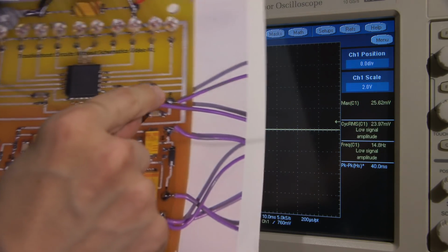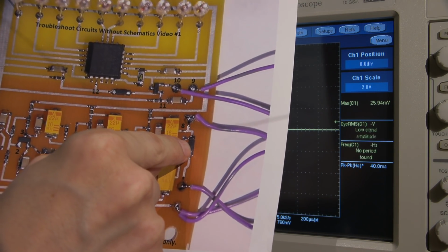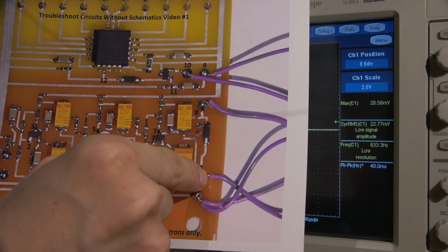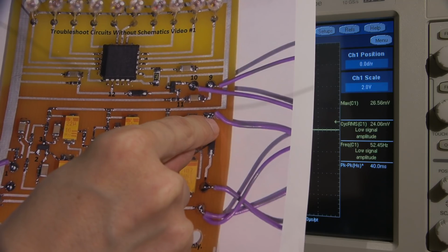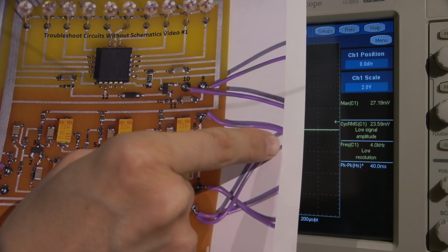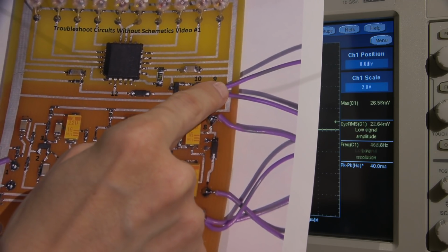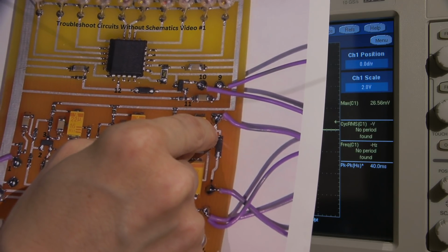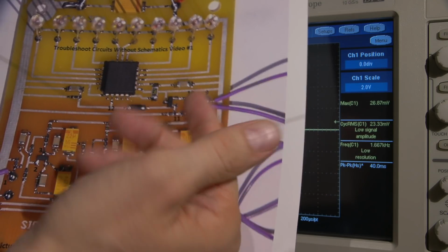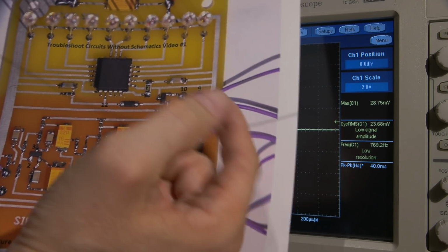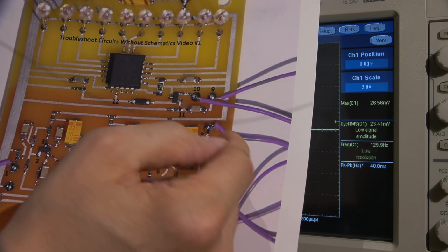Since we have this present at this point here, the anode end of the diode is connected to ground. So we have the cathode end, which is the line end facing up here. We know that this is going to run through a VR and then a switch and then back out to this point over here. Now, we can very easily verify that by just following the wires to the switch. Again, if you want to follow the schematic at this point, you're welcome to do that.